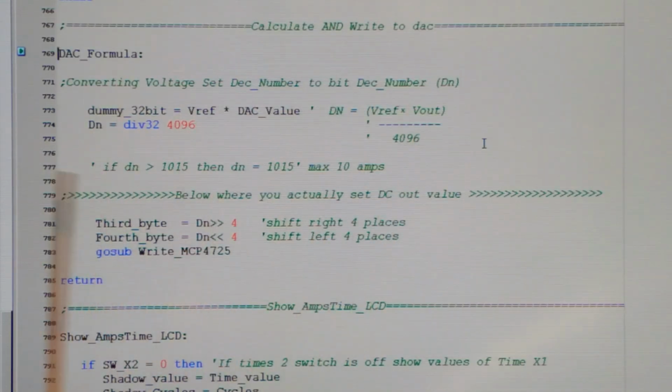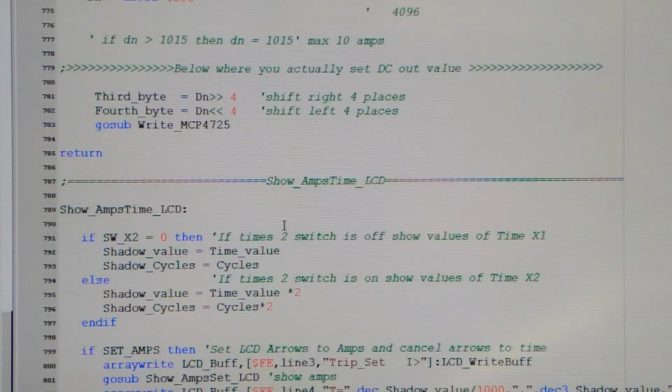And once you've done your calculation, then load up your decimal number into the bits of the DAC. It's using the 3rd byte and the 4th byte. That's regarding the register bytes of the MCP4725. And people of Arduino use the same system here. Okay, it's written pretty much in the same way. That's the quickest sort of way you could do it, by shifting the bits.